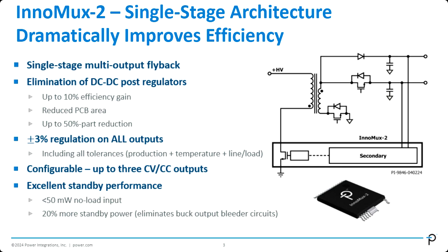What's a typical switching frequency? Typical switching frequency depends on the output loading condition. But normally at full load, it depends on the primary switch. For the GaN part, we can allow up to 130 kilohertz at steady state switching frequency. But with MOSFET, we can only allow up to 100 kilohertz switching frequency at steady state. So it really varies depending on your load condition.